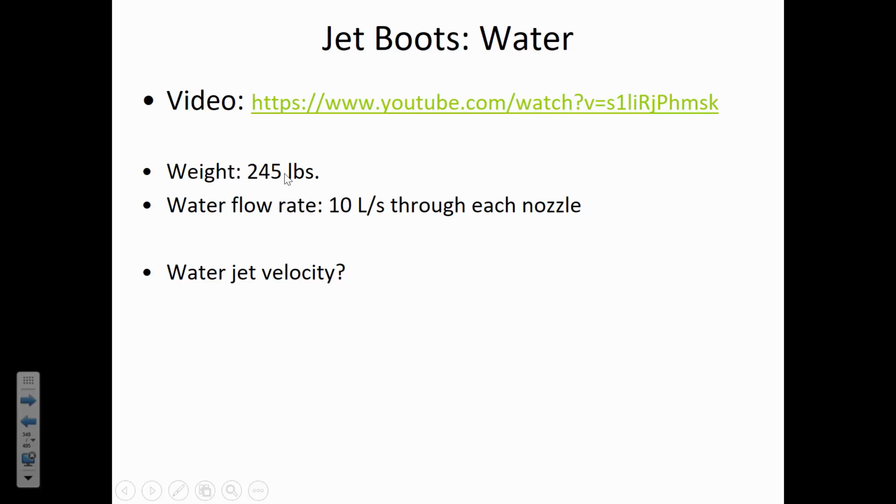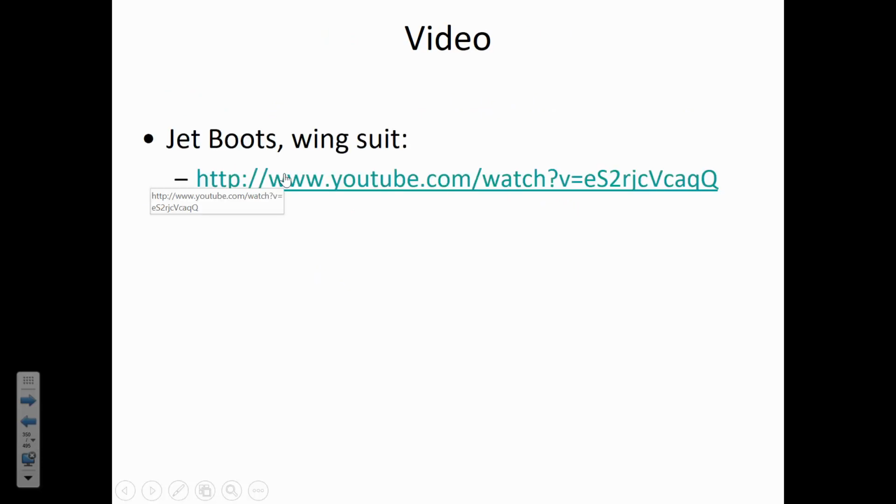Now the reality is that with the thumb trigger, when the person increases the flow rate, they're simultaneously increasing the mass flow rate and also the velocity. So both of those things go up as the pump inside the wave runner increases. But it's an interesting application of the momentum equation. Let's look at another one.